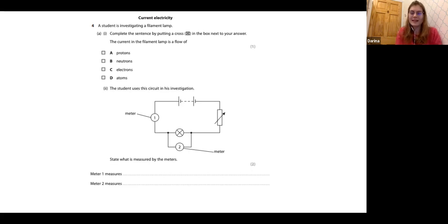Right, we've got some answers already. Anyone else have ideas? Right, so great. Obviously we already have a voltmeter and an ammeter in this circuit, so it's actually quite simple what we do. What we use is just Ohm's law. We do the voltage that we read off the voltmeter divided by the current that we read off the ammeter.